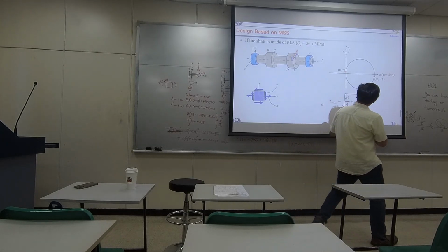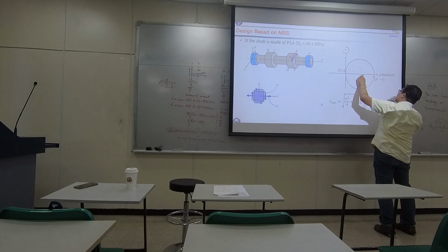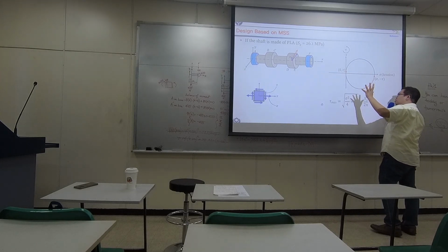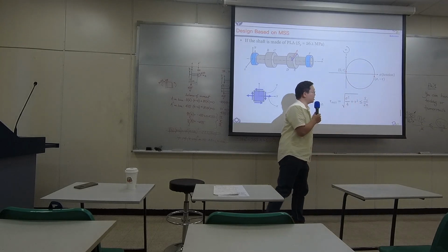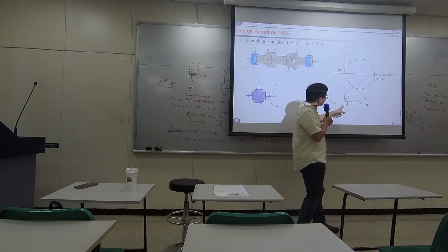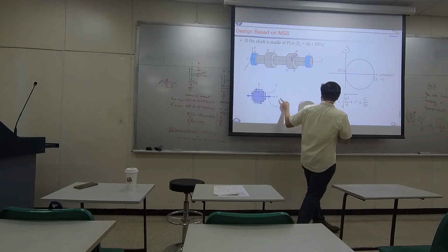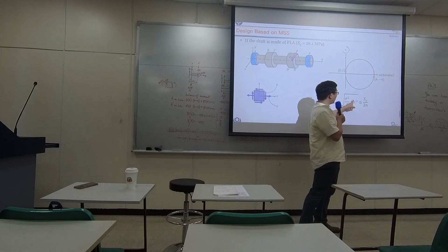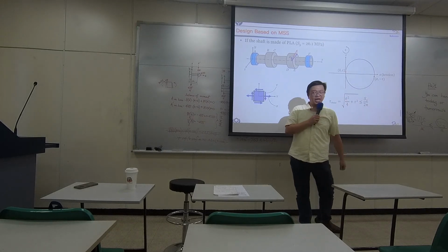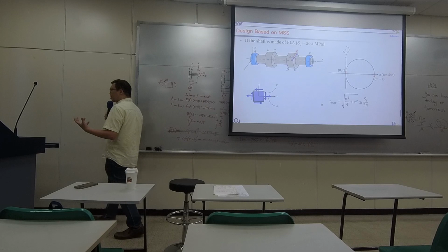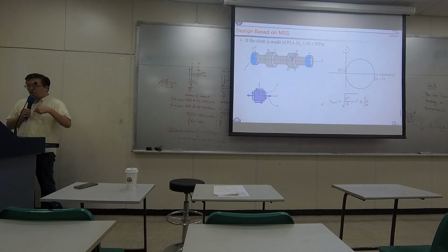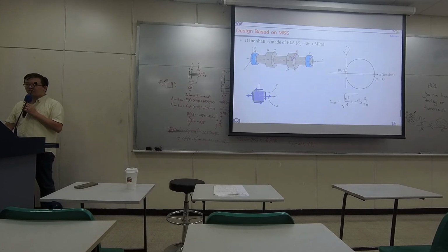So if you try to compute the radius of this Mohr circle, the equation looks like this. Your design equation is going to be whatever your normal stress is squared over 4 plus whatever shear stress you have on the right-hand side squared, and then square root, smaller than whatever shear stress you have over 2n. So it's more like a general equation in a particular shaft problem.